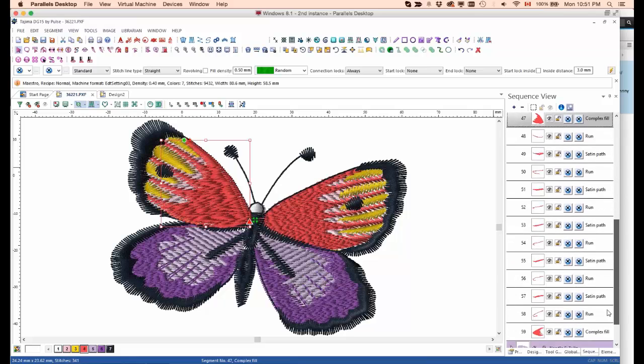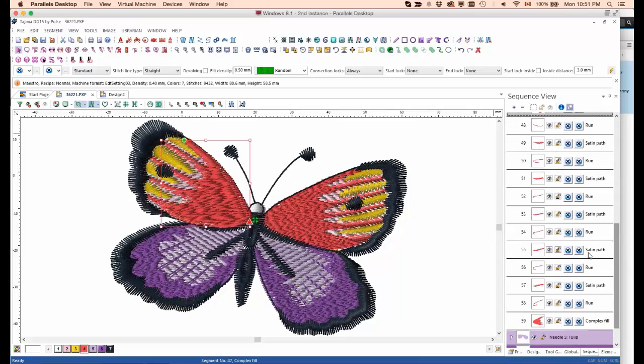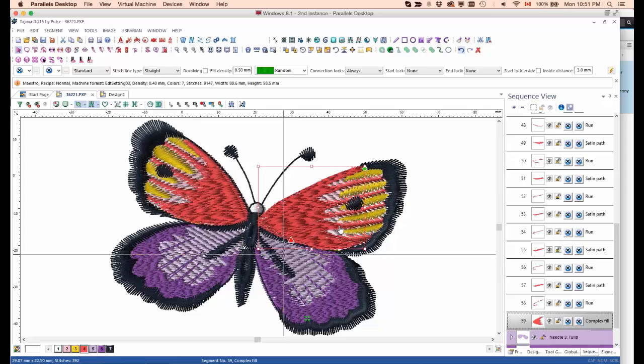All right. So maybe at this point, I will also use a feature that I guess some of you know, some of you probably don't. It's called the settings painter. You see I've changed the randomness of the pattern of this wing of the butterfly. I want to apply that to the other wing as well. So I select the segment, click on the settings painter. Basically I'm copying the settings, and then I select the other wing and I'm pasting those settings. You see now the wing on the right hand side has the exact same parameters.